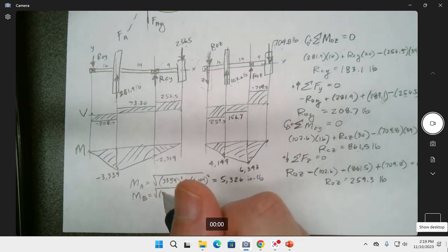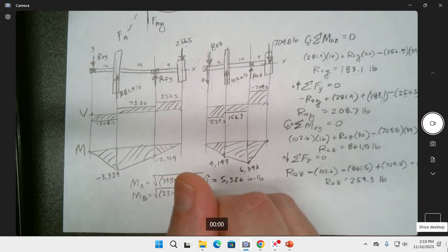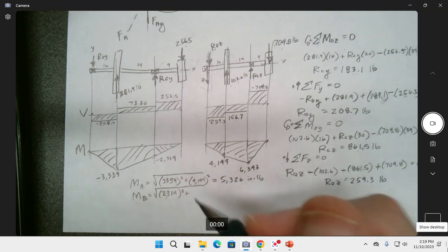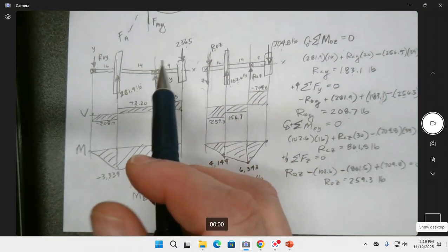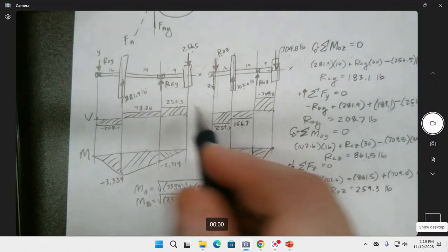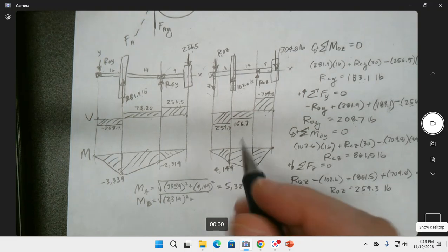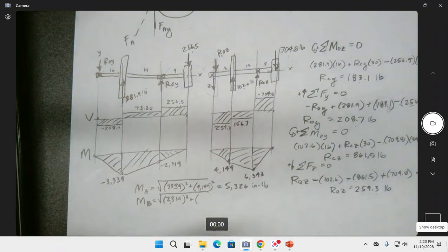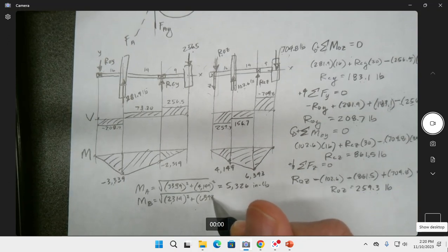Because that cantilever thing is also the length of these shafts. Unless there's some machine it's attached to and you don't have any amount of control over where you place these gears, you would not make shaft lengths this long. You want to keep the distance between the gears and the bearings short. So it's just some kind of miscommunication going on between the designers on different teams.